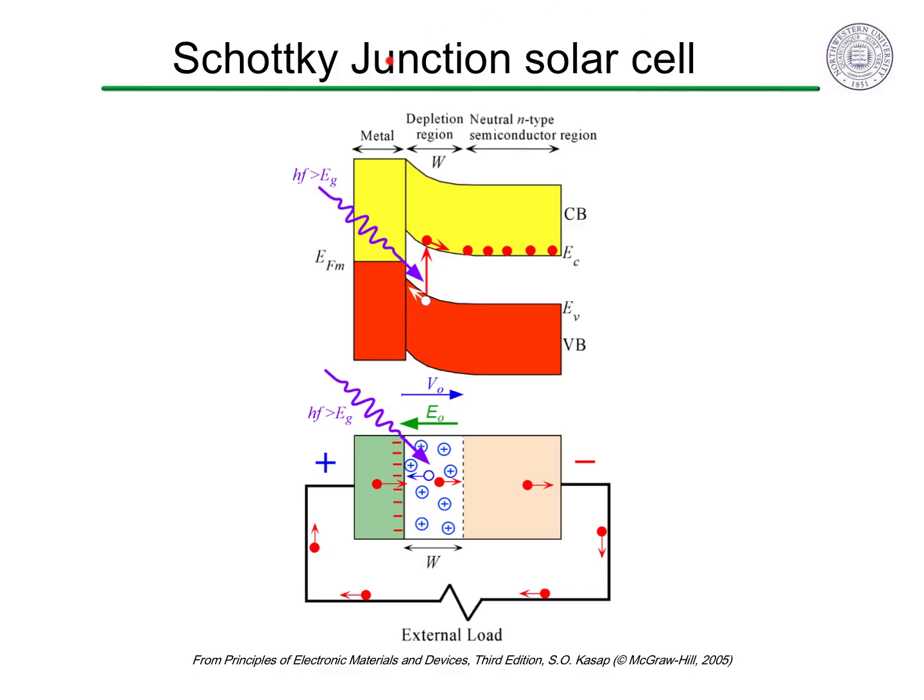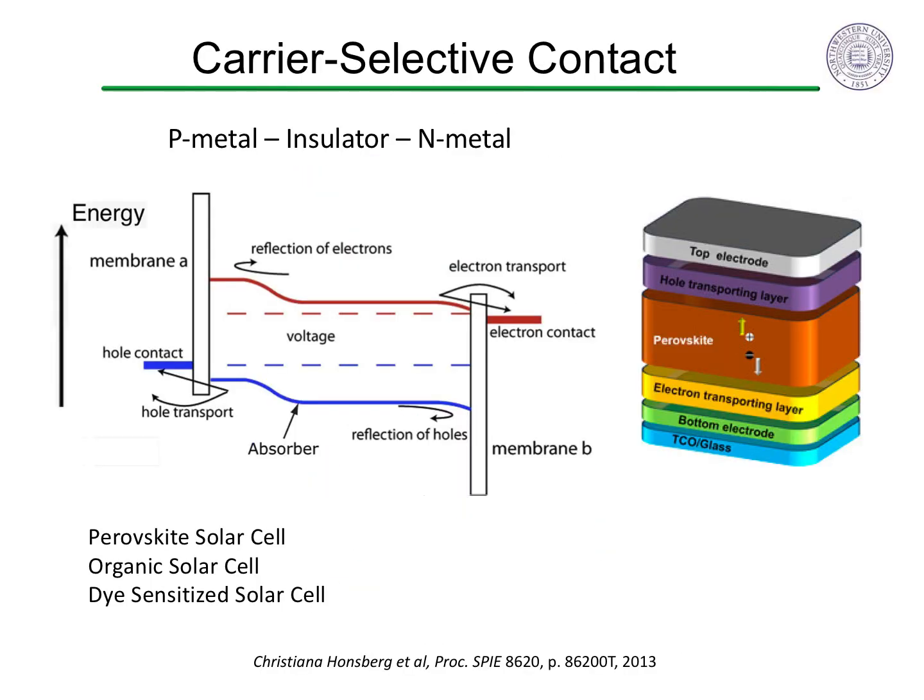Schottky junctions can also be used as a solar cell. The junction produces a small depletion layer and thus a built-in voltage, which can be used to separate photogenerated electron-hole pairs. Here, the electrons slide down, making the semiconductor the negative electrode, while the holes float up to make the metal a positive electrode. Many of the emerging PV materials, such as perovskite solar cells, organic solar cells, and dye-sensitized solar cells, have no explicit p-n junction.